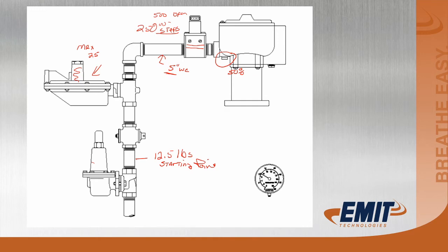You want to measure this. And when you're measuring fuel pressure, here's your water manometer, you always want to measure between the pre-side of the carburetor and the fuel side of the carburetor. That's your air over fuel. And you want that fuel pressure to maintain that 5 inches of water column.